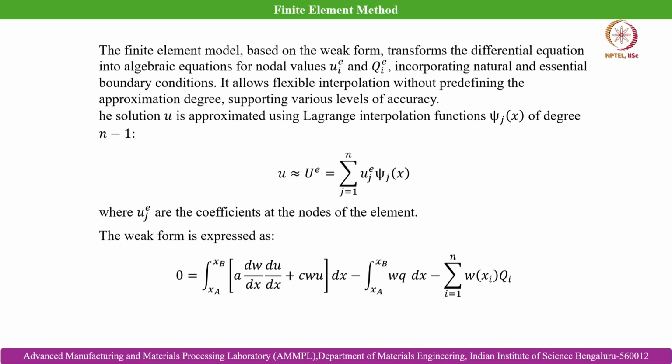Arriving at the set of finite element equations at each nodal point of a given element based on the PDE, the governing equation that we are solving in the domain. So the finite element model based on the weak form transforms the differential equation into algebraic equations for nodal values u_i^e, the primary variable, and secondary variable q_i^e, incorporating natural and essential boundary conditions. It allows flexible interpolation without predefining the approximation degree, supporting various levels of accuracy.